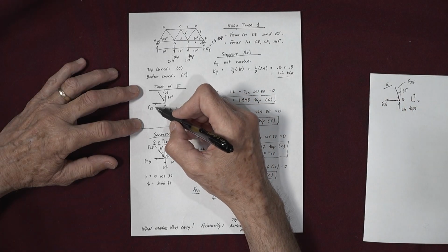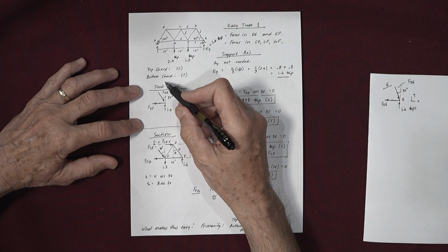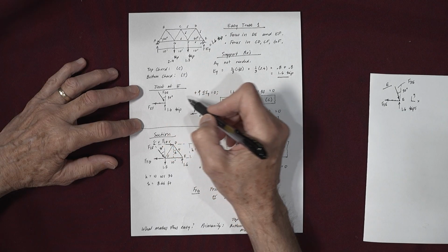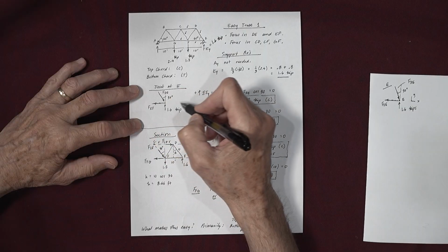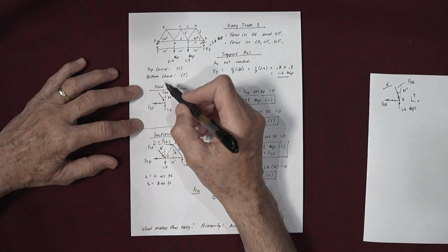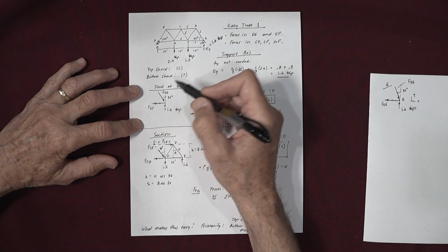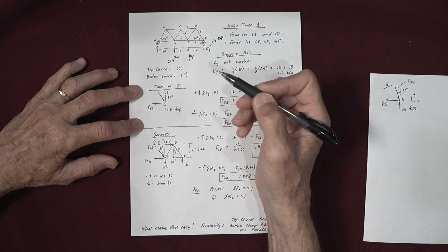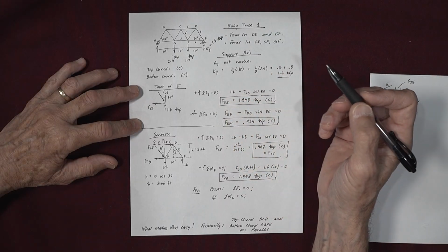So once you draw the free body diagram, we can write two equations of equilibrium, usually a y summation and an x summation. If we write the x equation first, there's actually two unknowns in the x equation. So this guy and this guy are two unknowns. So the x equation doesn't get me anything yet. And so I'm going to start with the y equation.